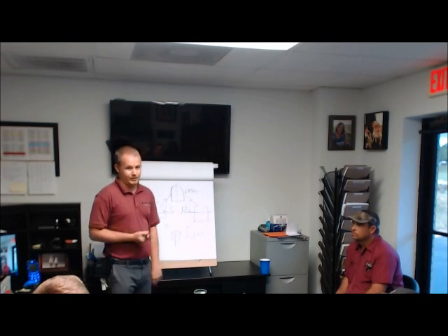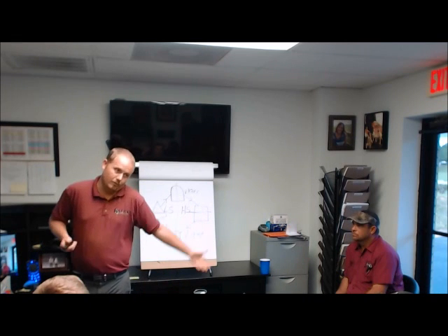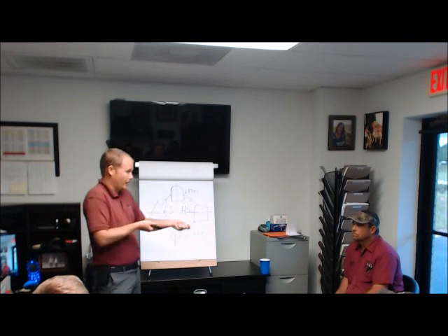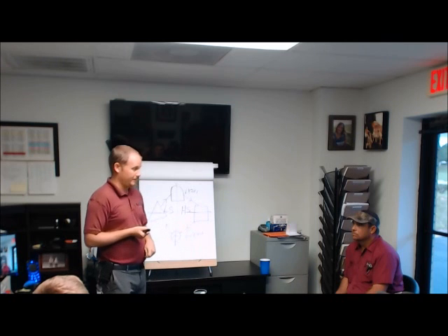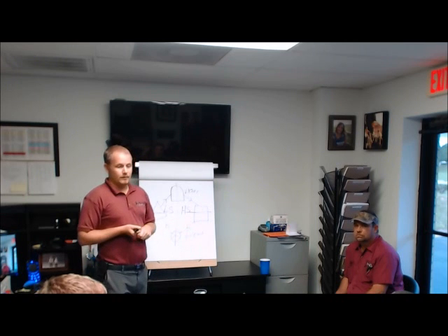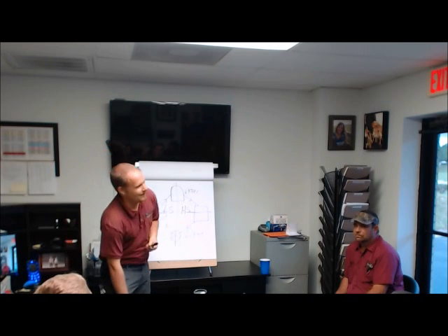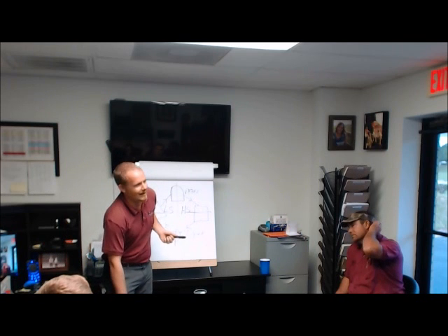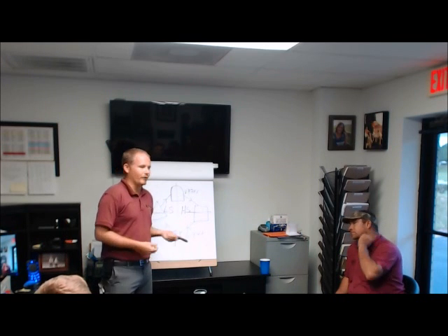If you had a sight glass, you could tell, right? But we don't. So we gotta use our temperatures and our pressures in order to tell us whether or not we have full liquid here. Isn't it industry standard to put sight glasses on everything? Because they really don't have any point, honestly. The only point of a sight glass is for people who don't know how to read subcool.